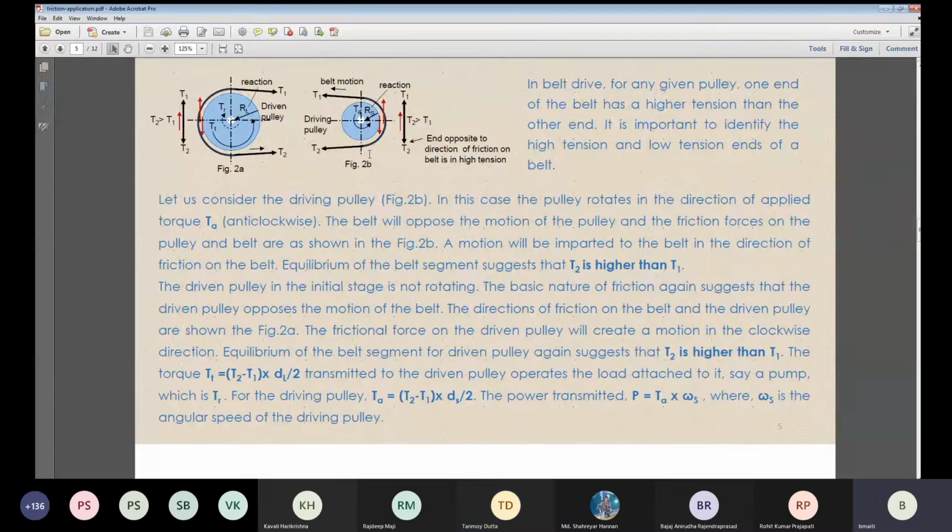That's the way the pulley sizes are determined. My requirement is running, driving an equipment. Now I have to adjust the pulley diameter such that it gives that particular speed of rotation, knowing that in 99% of cases 1440 rpm motors are available. So accordingly I have to choose the driving pulley and driven pulley size to adjust the rotational speed of the actual load I intend to run through this belt drive. Is it clear? Fine. Yes, sir, got it.